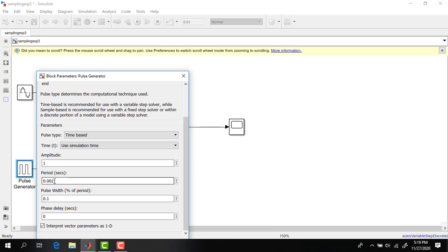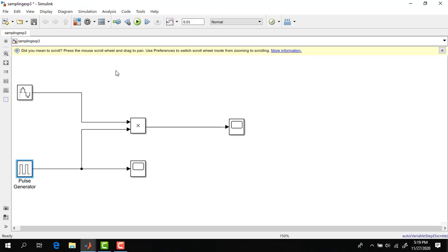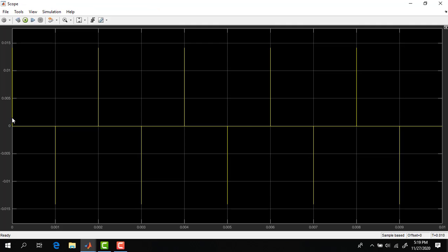But if you keep it at least twice the original signal frequency, if you keep it at 0.001, which is the Nyquist rate, you can actually feel a bit of resemblance with the original signal. You can see it is not perfect, but if I tell you that this came from a sine wave, you would believe it, because if you have a good imagination, you can see that this signal was hovering in this direction, right? Yeah. If I just draw it for you.